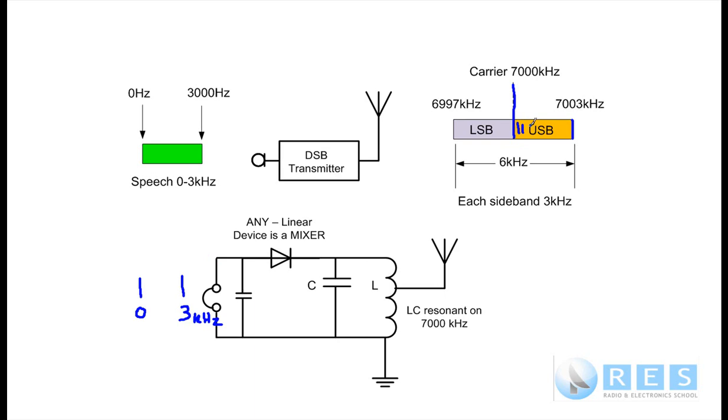And each radio frequency signal in there will be converted to a difference frequency, the difference between 7,000 and all these individual frequencies, and I'm going to draw them in. But it would be easier if I just drew a rectangle, and it would be even easier if I drew the rectangle that I have above, because that's exactly what it is.